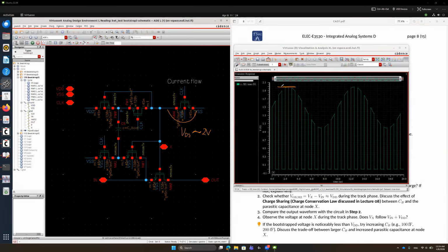If it touches as high as 2 volts, that means after we fabricate this chip, this transistor may die. Die means that the drain to source connection may be irreversibly damaged such that source and drain are shorted, and then we cannot recover it. So that kind of situation is not prepared for.